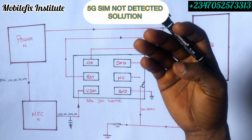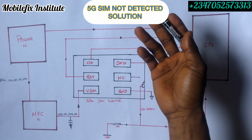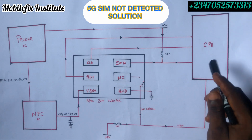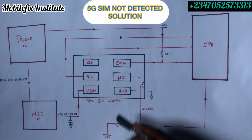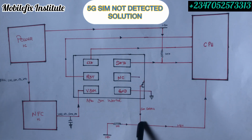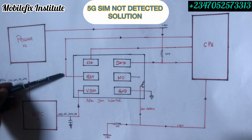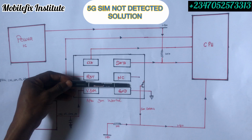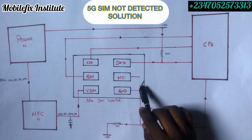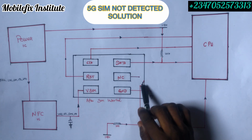And this is how this line works. Even when your phone is on and you insert your SIM card, your CPU will detect immediately that you have put in a SIM card, and then it will indicate. It is this SIM detection line that is working. Now, in most phones, this line is always connected to ground, this pin.